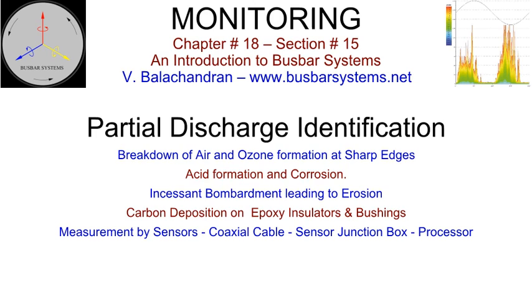Sensor junction box. All the coaxial cables from the individual sensors are grouped at one location and connected to a processor by a multi-core cable. Processor. The inputs are digitized, processed, and transmitted to a computer for monitoring.